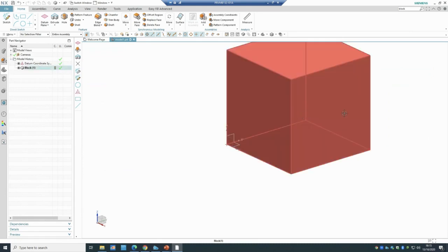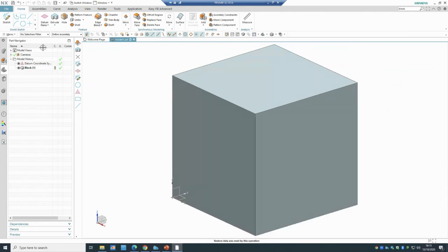Great. So now I'm going to talk about the planes. If I go to the filter, if I go to the face, you see these are the filters you would be able to use. If you want to use the coordinate system, you can come here. If you want to pick the edge, you can. I'm going to pick the face. Each of these has a plane. So whenever I'm going to do a sketch, on each of the sides, of course, I can use it as the reference for my plane. And let's say I'm going to create a plane exactly on top of the cube that I have, which we call invert.